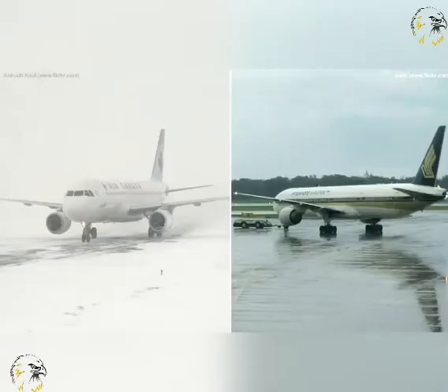Now let us move to the subject of runway contamination, which in this case means water in its various forms lying on the surface of the runway. These forms are frozen water, that is ice and snow, melting snow, that is slush, which can also be formed by a mixture of rain and snow, and liquid water. Just as we remember the problems of our first attempt at ice skating, so aircraft may suffer issues of directional control and, of course, stopping.